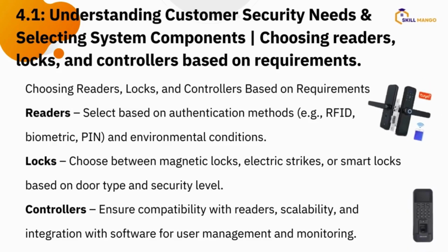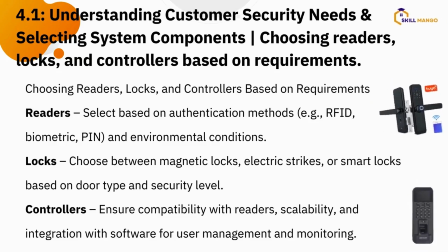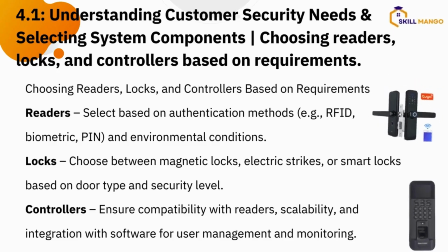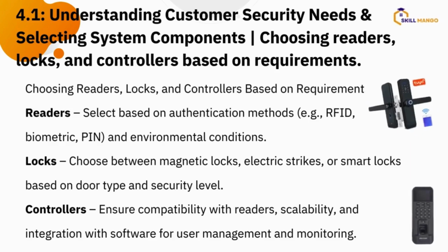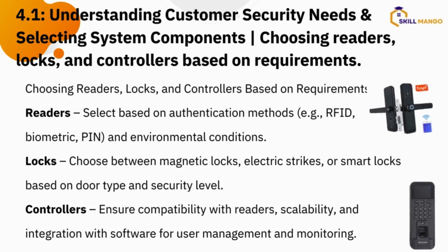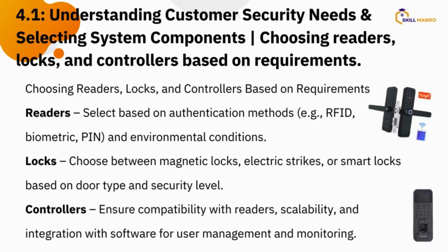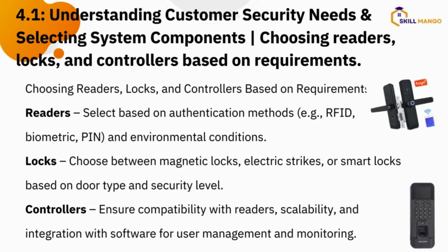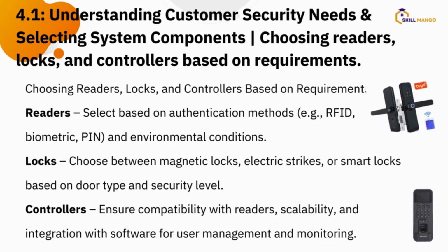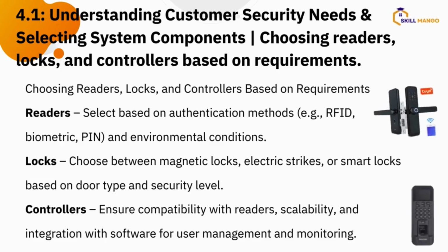So in my own opinion, I would go with mag lock because mag lock is, in case of emergency or power outage, everywhere opens. So you can know that okay, people can go in and out. But for electric strike, it stays locked until you get somebody that has access or you get the exit button to disengage. All right. Then if there is a power outage, it's still locked until they bring in the power or you power the backup or the backup system is working.